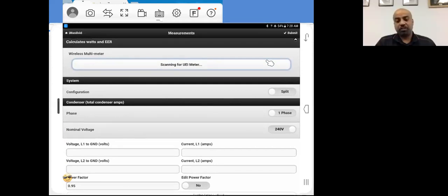And another thing you can use the DL429 on is when you're checking those compressors, you can measure all the capacitors as well, as long as it's all disconnected. And if you've drained the capacitors, you can use the DL429 on the capacitance feature to test all the capacitors on the compressors as well.